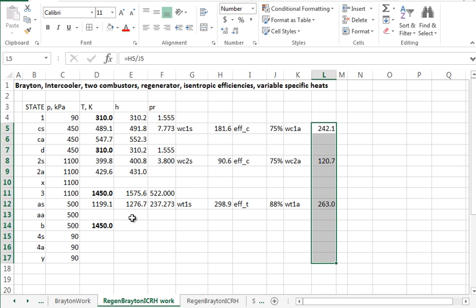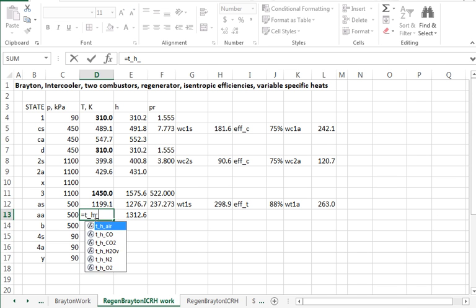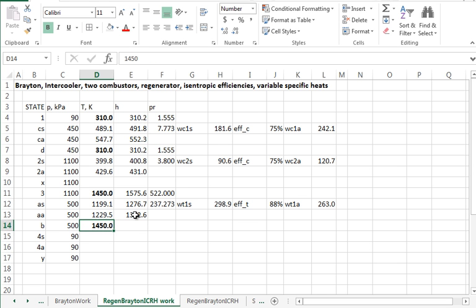Okay. And so then I can get the enthalpy. It says the inlet enthalpy minus the work extracted out. And so there's the exit enthalpy. Knowing the exit enthalpy, I don't need the Pr, leave it alone. I can get the temperature. Temperature is a function of enthalpy for air. Boom. All right.